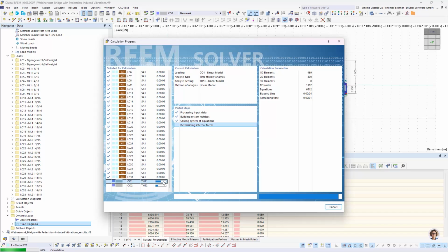And the problem with this first one is we only have global damping, so either Rayleigh or Caughey damping. That's a problem as well as a benefit, right? We have a simplified possibility for considering global damping, but at the same time, we can't use local dampers. Local dampers are only available within the direct time integration. So there are damping problems and benefits in both variants.